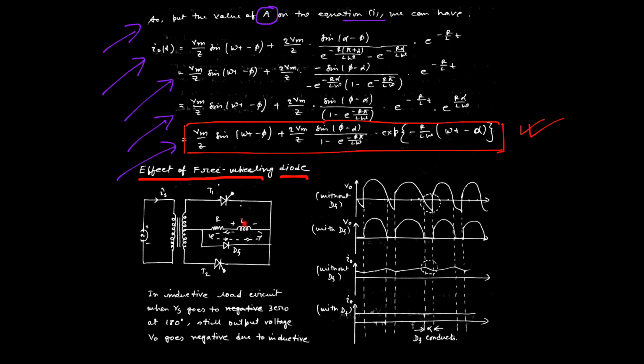Okay, this is a schematic circuit diagram in which we are using the RL load as well as the freewheeling diode. By using this freewheeling diode, the negative peak that appears due to the discharging path of the inductor is not fed back to the supply. The current freewheels due to the presence of the freewheeling diode across the load. That is why there is no question of this negative peak. Okay, so we can illustrate the total discussion by these waveforms also.